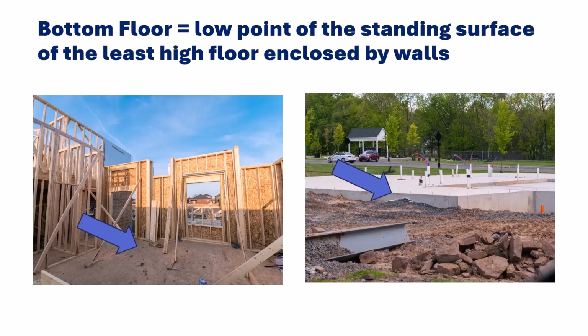The bottom floor, measured typically in Section C of the elevation certificate, is objectively measured by the surveyor. It simply is what it is. It's the least high point of the standing surface of the least high floor of a building that's enclosed by walls.